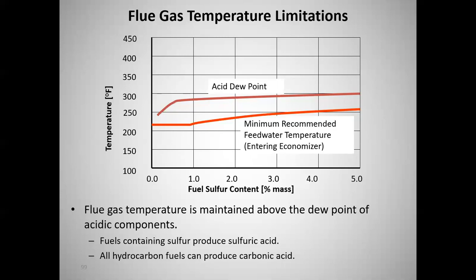And so there's two things. You see sulfur listed on here. So if you have a fuel that has sulfur content, as you cool flue gases, it'll burn to what? Sulfur dioxide, but it will condense as sulfuric acid. It will condense to H2SO4. And y'all know from your chemistry lab, sulfuric acid loves to eat a hole in things, and it'll be quite concentrated, okay? So that's, as you start to cool down, our first point at which we have to worry about stopping in terms of cooling the gases.